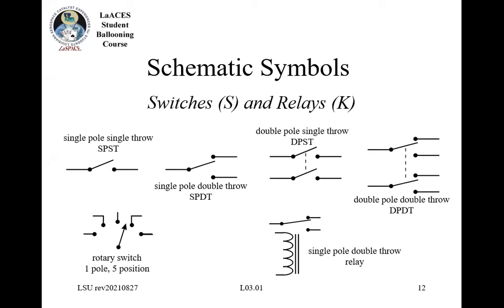Normally you see relays used to switch power. Sometimes you see them switch signals. But if I have a power line down here that I'm switching between on and off, then I can also get a little status bit that I run into a digital logic line that tells me if this relay switched. So that's a way you can use that. But oftentimes you'll just see these other ones for simple things. There's also something called a rotary switch. So that kind of has a dial on it. So that may be the symbol for that.